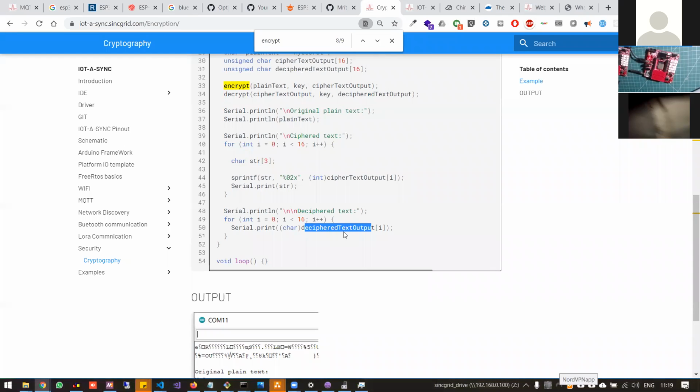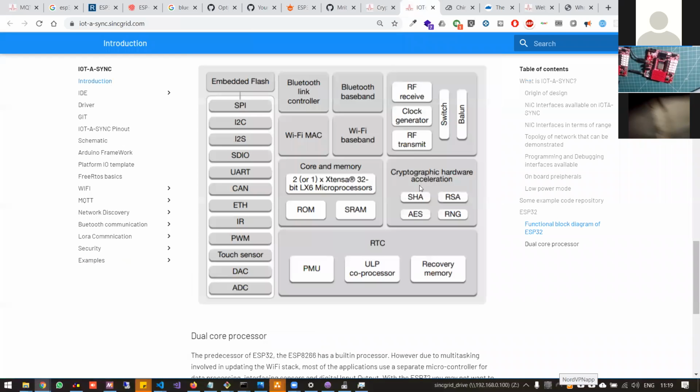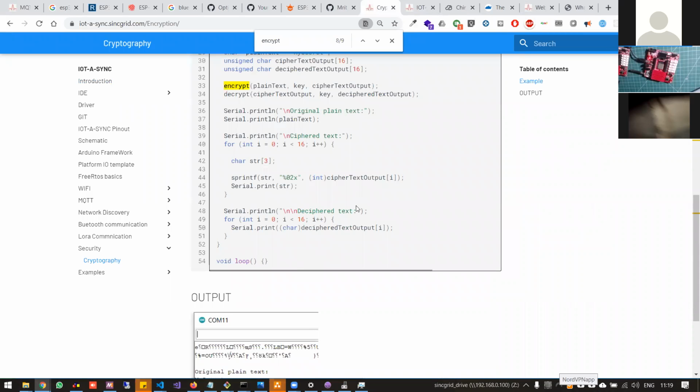So if you want to communicate these kinds of devices to AWS IoT Core, for example, whatever the PEM file or the keys, SHA keys, or the security module that they provide, we need for the communication. We need these kinds of blocks to maintain a secure TLS communication and to decrypt and encrypt using these accelerated cryptographic blocks. These blocks are used by the secure connection to receive and send packets. So this is a basic example.